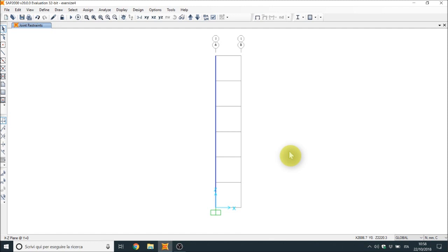In the Eurocode, you can give the imperfection by using a deformed frame or by using equivalent forces. So I did the same thing. I give my beam an initial configuration with forces, so a deformed shape configuration.